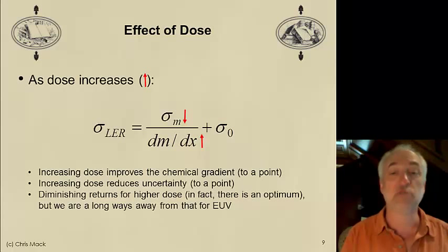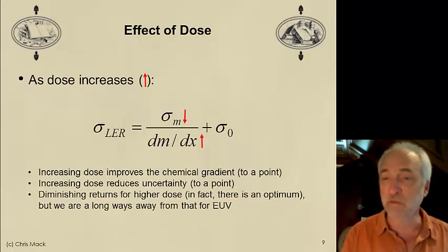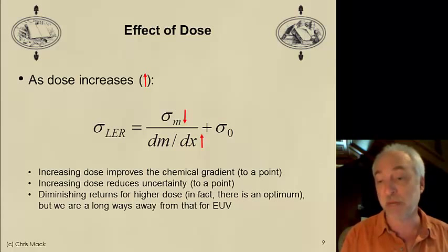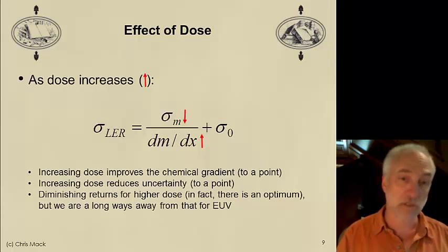And certainly that's true for EUV, because we have so few EUV photons available to us. We're always trying to expose at minimum amounts of dose, and so higher doses are going to make LER better.